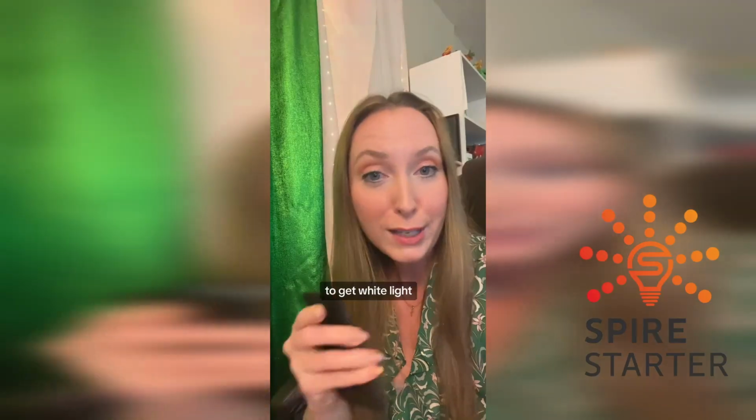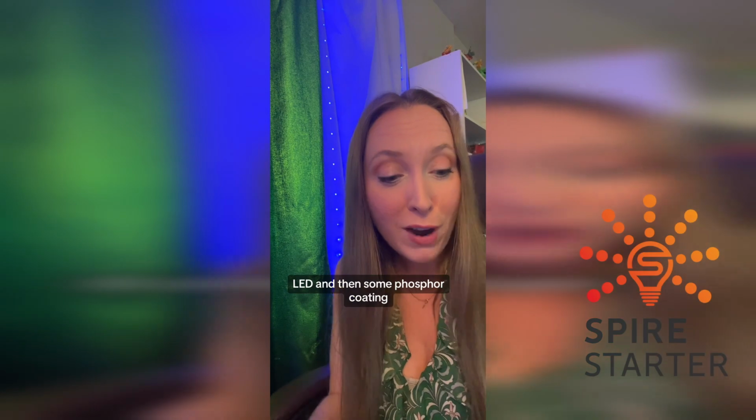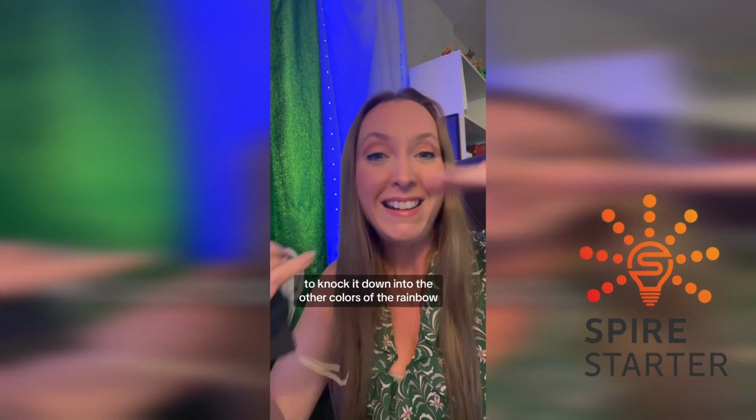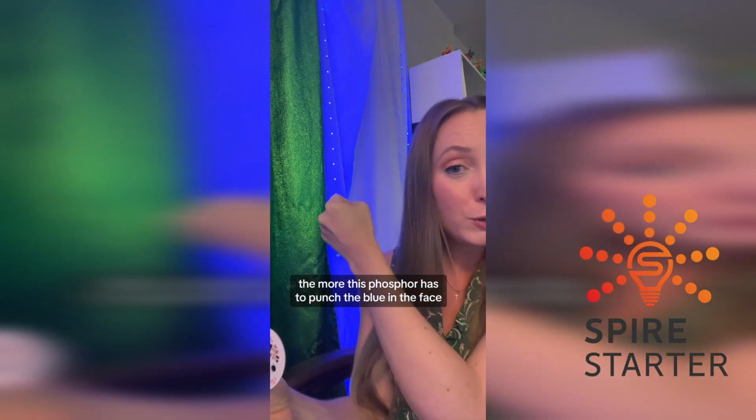So why is that? To get white light with these LEDs, it starts with a blue LED and then some phosphor coating, this yellow stuff, is put on top to knock it down into the other colors of the rainbow so that it mixes together and gives you white. The more this phosphor has to punch the blue in the face and knock it down a peg into the other wavelengths, the more energy it loses.